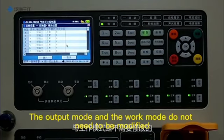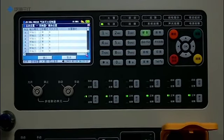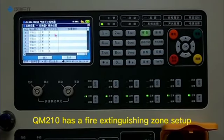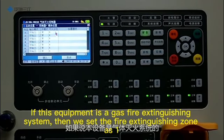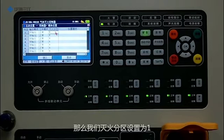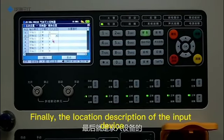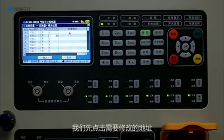The output mode and the work mode do not need to be modified. QM210 has a fire extinguishing zone setup. If this equipment is a gas fire extinguishing system, then we set the fire extinguishing zone as E. If not, we can just set with U. Finally, the location description of the input device.